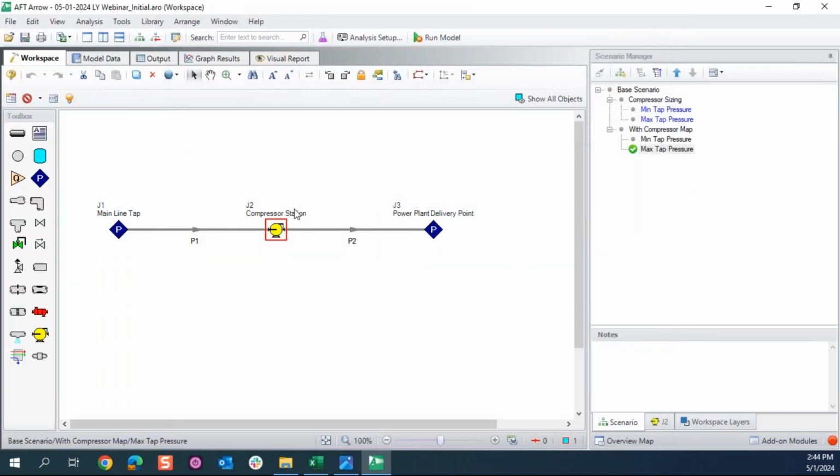So next thing I wanted to kind of go over was something that I ran into when I was first building out my model, which was compressor maps tend to have a lot of operating conditions that can satisfy a system, which can make it mathematically challenging to find the exact solution that works for your system.